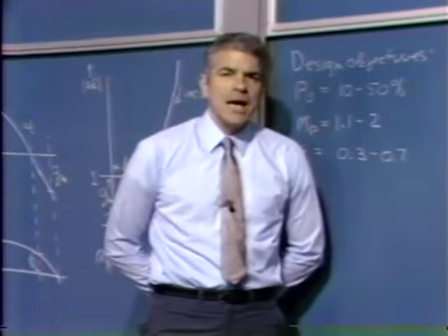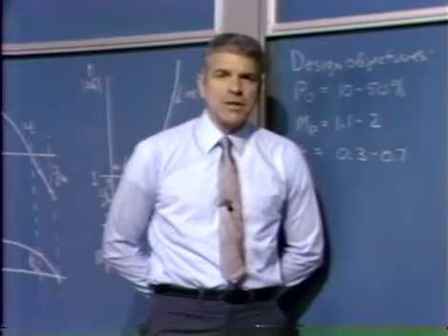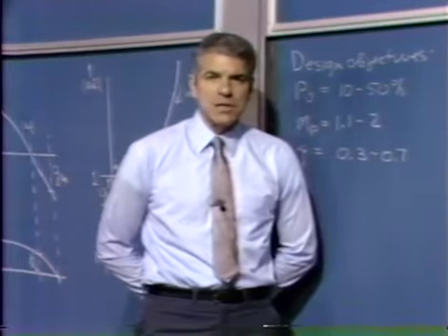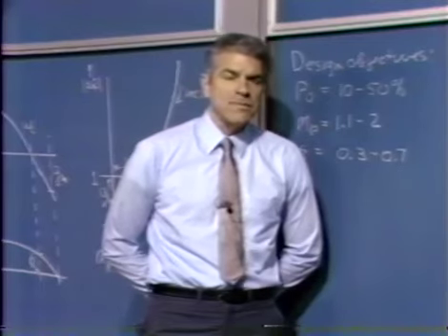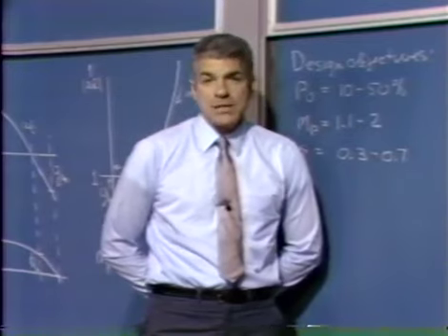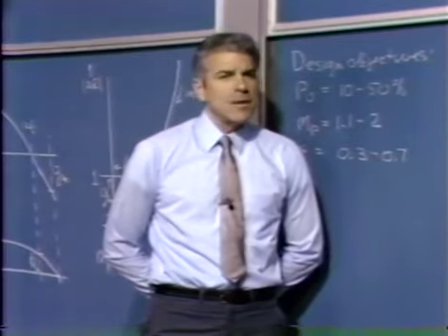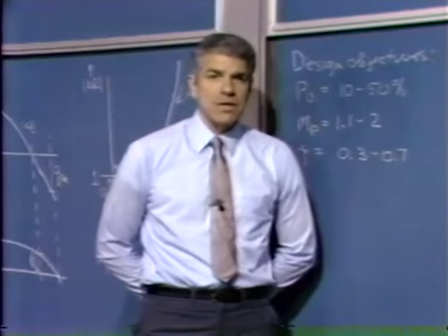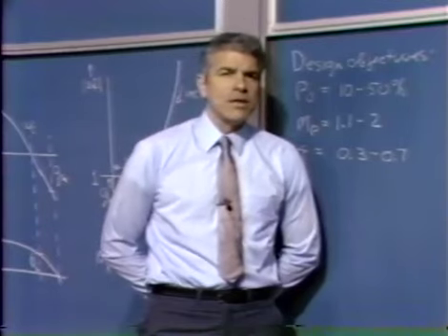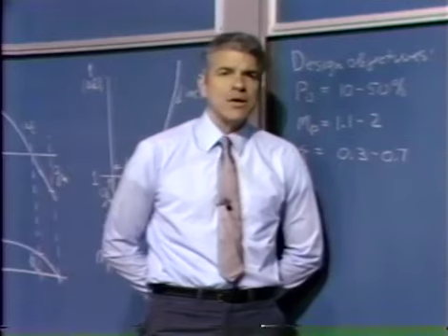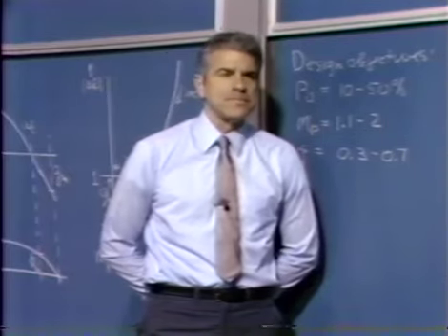with relatively little trouble. However, if we consider an operational amplifier, and in particular a very fast operational amplifier, maybe an amplifier that has 100 megahertz unity gain frequency, and such operational amplifiers exist, then if we want to increase the loop transmission magnitude, basically we have to add another stage. And that may be very difficult to do without dramatically changing the nature of the phase curve. So in that case, we have relatively less freedom in the manipulations we can do with the A0 F0 product, because changing the A0 F0 product affects something else.